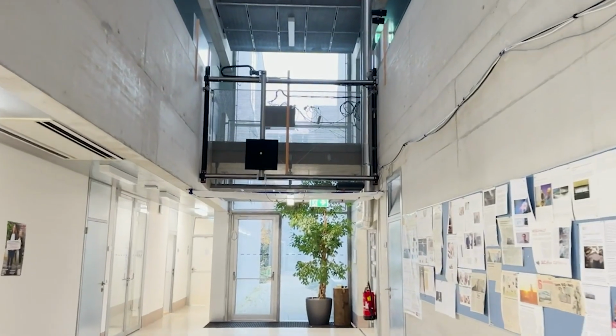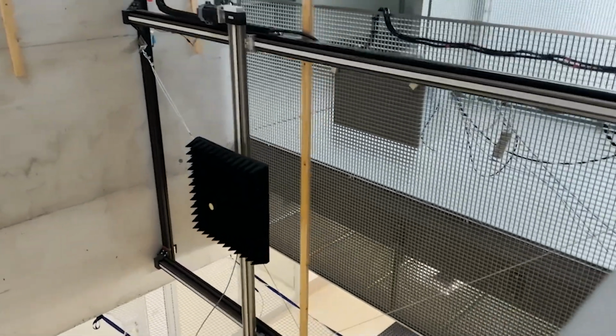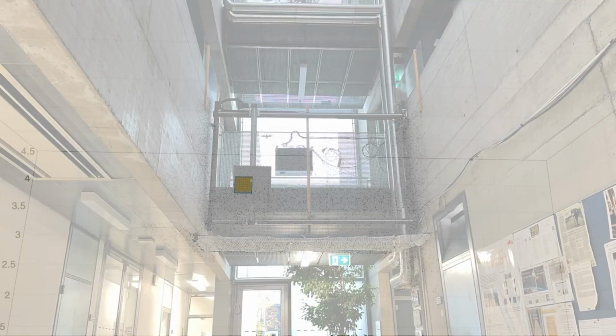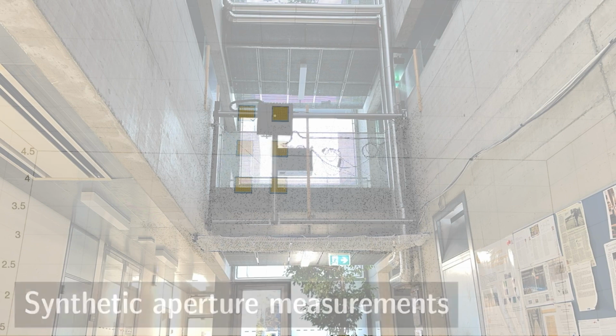Future distributed radio infrastructures hold promising potential for positioning and mapping, which can be leveraged for efficient beamforming and robust communication even under user mobility. We acquire synthetic aperture channel measurements in a realistic hallway scenario, where we subsequently measure the channels from a single antenna agent to 15 anchors, each equipped with an 8x8 antenna array.